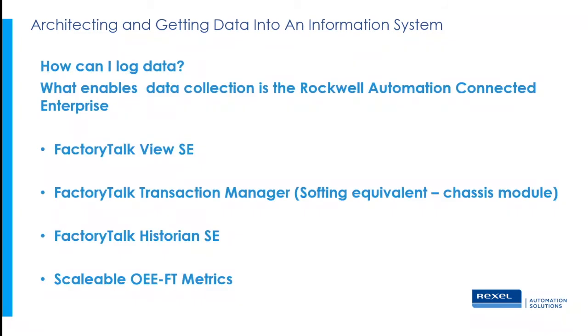So how can I log data? I'll be looking at 4 specific Rockwell Automation software products that enable us to collect data and visualize. So we'll be talking about FactoryTalk View Site Edition. That's our SCADA package. Another software package we can use is FactoryTalk Transaction Manager. Allows us to log data. There's a module chassis-based equivalent from Softing.